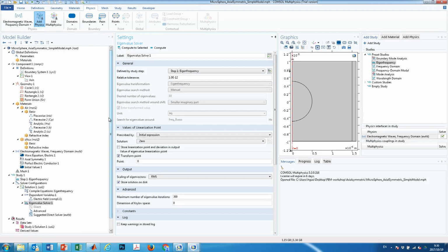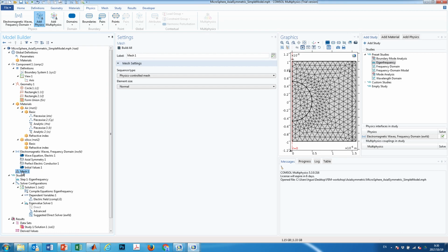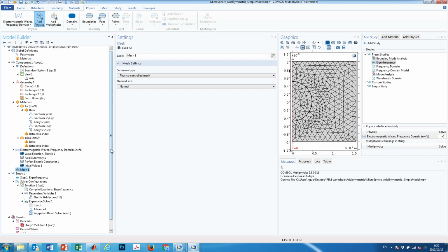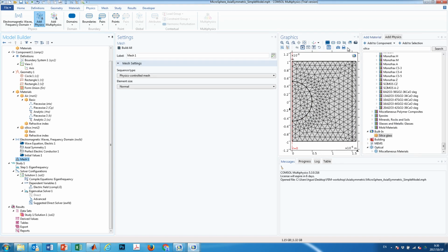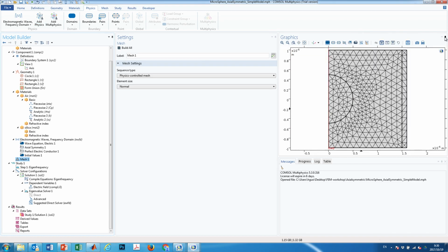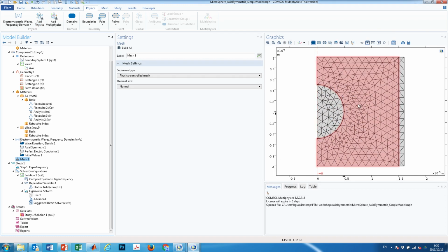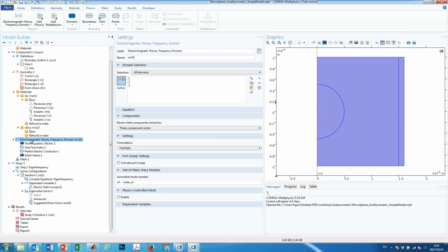Then what's missing is actually here the mesh. So the mesh is not properly set. I mean, you can see it's pretty bad. And definitely it will not be that precise eventually, even if the tolerance of the simulation can be very nice. But actually the mesh is very low, which means the geometry is indeed not well defined. So version 5 of COMSOL actually includes a physics-controlled mesh.